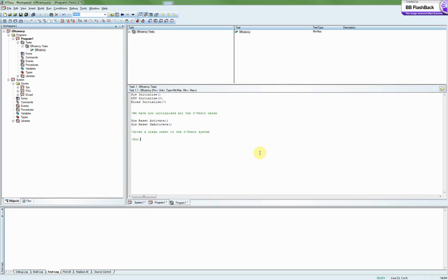So now let's set up the PSU. So if we say PSU and do space, you see we get many selections because there's not just power functions on board the power supply card, there's others. But we will go down, and the first thing we will make use of the protection features for the power supply card. So we will go to protection, we will go to set, and we will set the over voltage first.